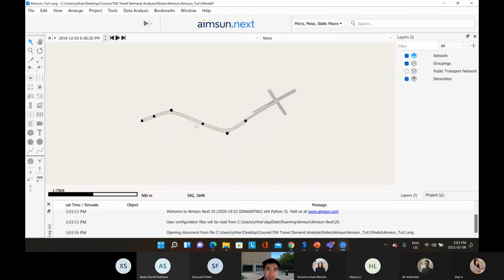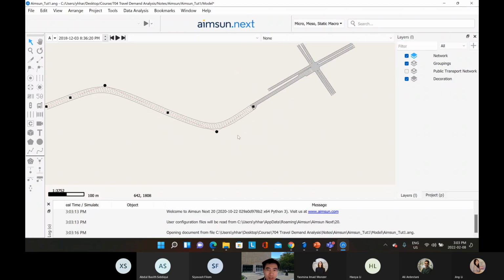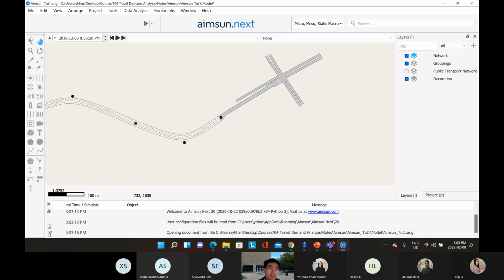designed. You may also notice that this one is a little bit large, so we can try to cut the section. If you think that the section is too long and you want to divide it into multiple sections, there's a trick for you to cut it. You see the knife sign here in the toolbar. It's called divide the section into two, and if we cut it multiple times, you get multiple sections. Before you use this tool, you need to select the section. Once it's selected, you cut it, and now it becomes two sections, which you can see here.